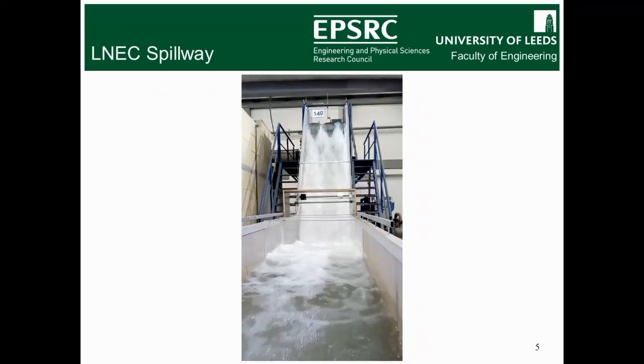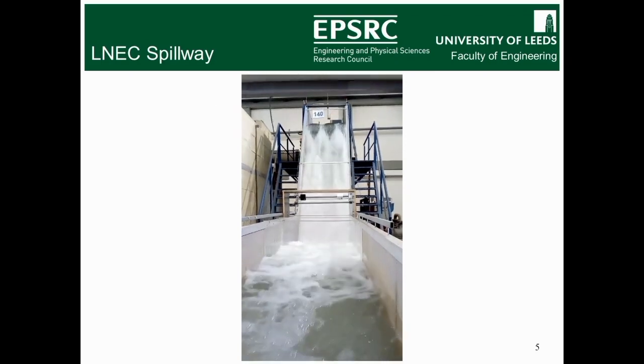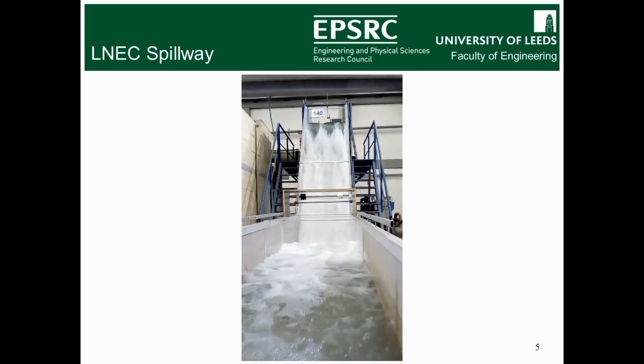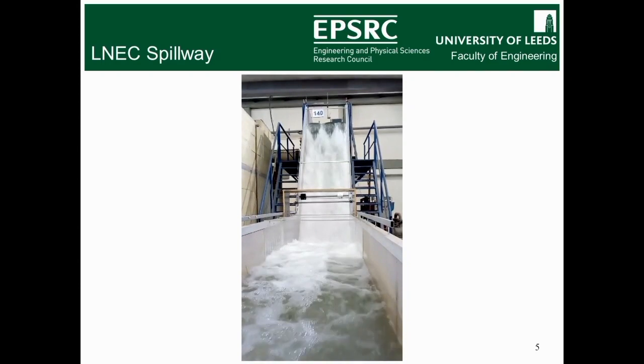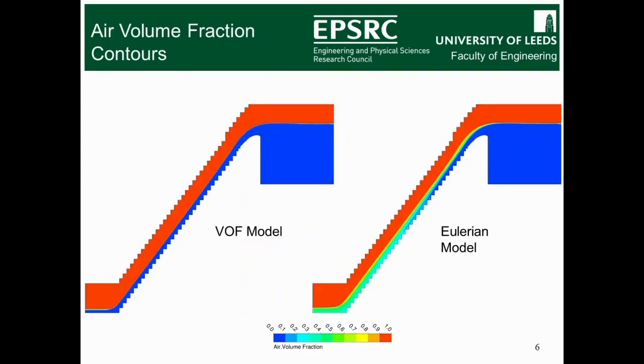The video's a little bit slow, but I've modelled two stepped spillways. This is the first one I've modelled, which is at the LNEC in Lisbon. It's a metre wide and consists of 33 steps, which are 80 mm tall by 60 mm long. And we've got some air volume fraction contours from the CFD models.